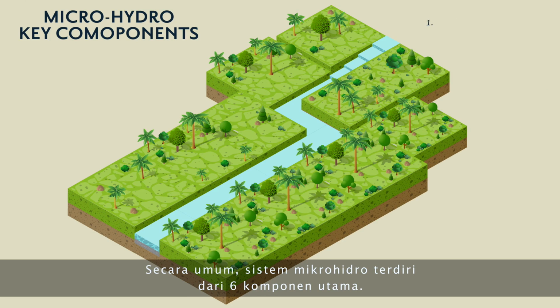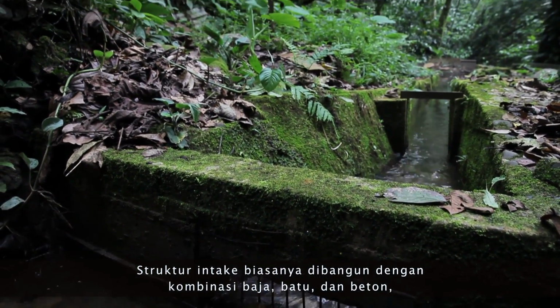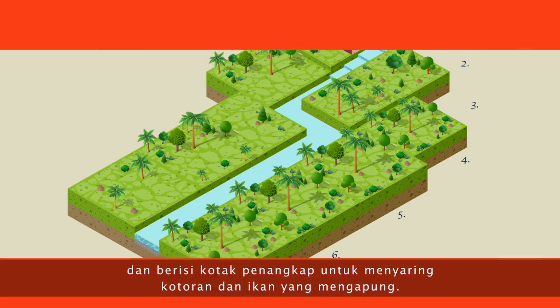In general, microhydro schemes are made up of 6 key components. The intake is where water is diverted into a dammed pool from a stream, river, or waterfall. The intake structure is normally constructed from a combination of steel, stone, and concrete, and contains a catch box with a screen to filter out floating debris and fish.